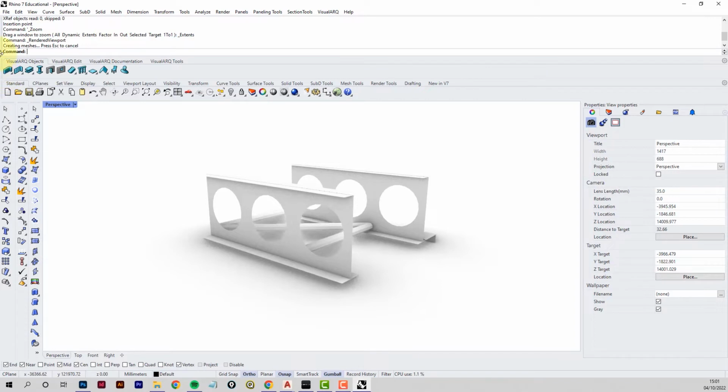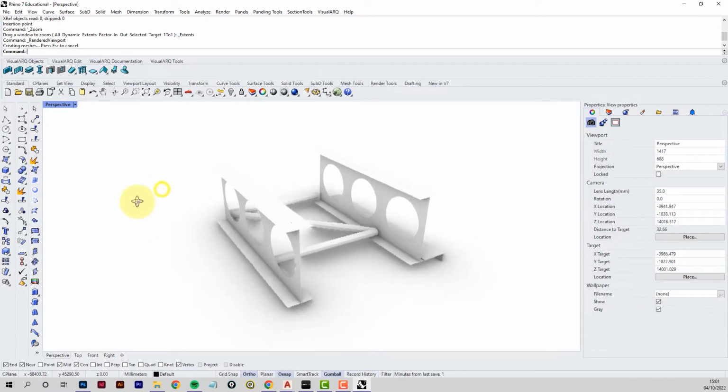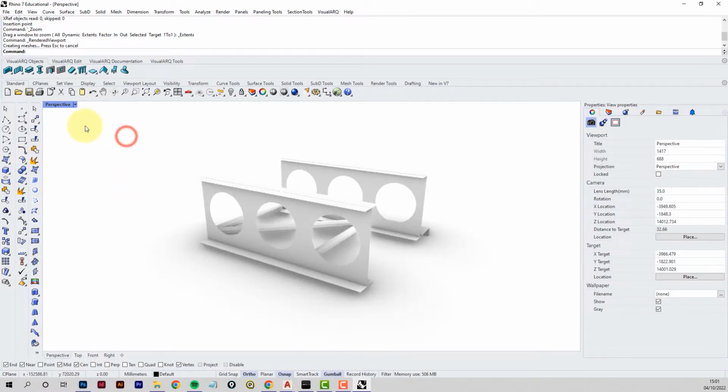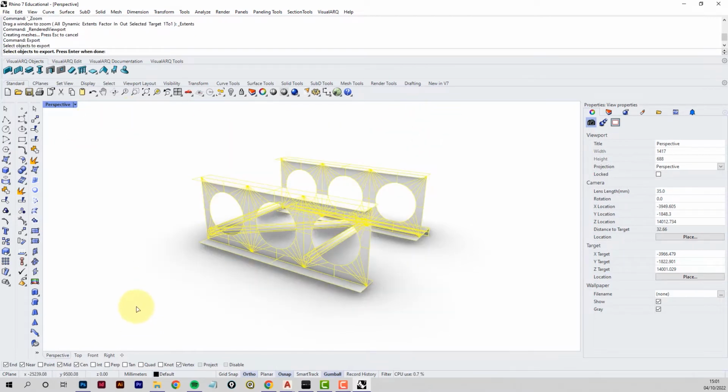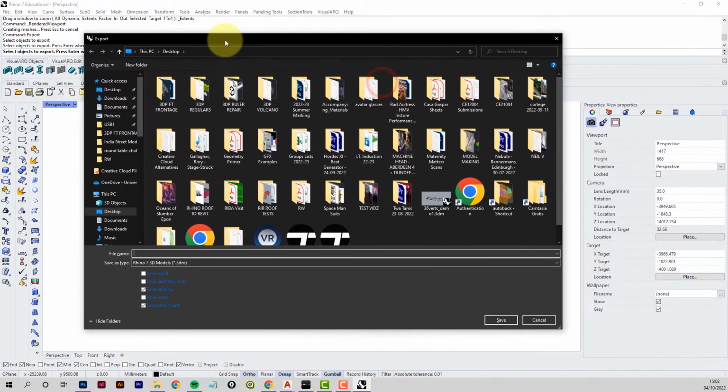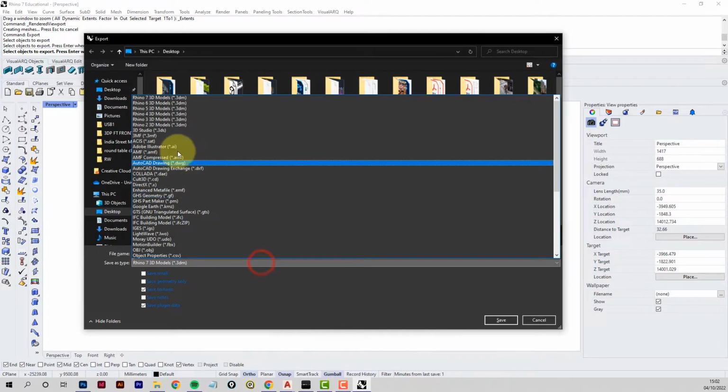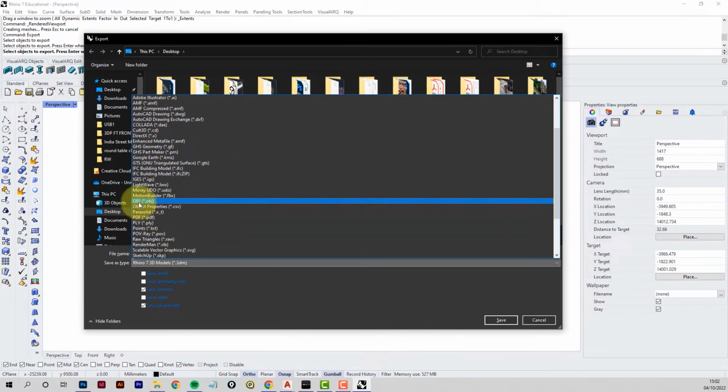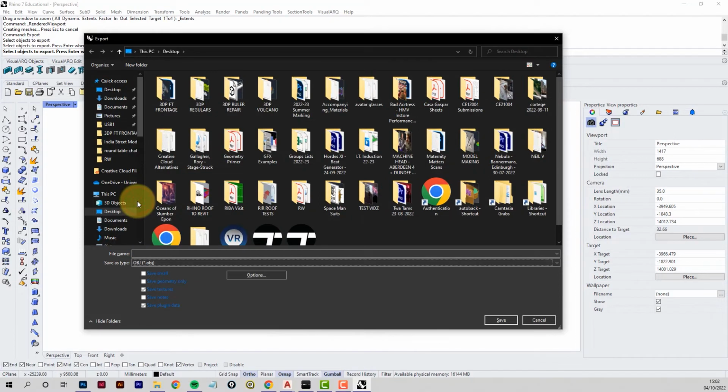Okay, I've brought the drawing into Rhino and just hit the shade button, and it looks quite seductive, looks quite cool. But what we'll do is export this. Select the objects. Okay, so we've got lots more options with Rhino. We can choose a huge number of different files, but OBJ is the other type of file that generally a 3D printer will work with. So we'll export this as an OBJ. Let's just call it Beams and Truss Mini. I'll keep the same name and save.